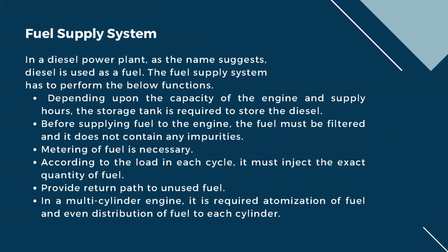The next one is, before supplying fuel to the engine, the fuel must be filtered so it does not contain any impurities. Next is metering of fuel is necessary. Next is, according to the load in each cycle, it must inject the exact quantity of fuel. Next is to provide a return path to unused fuel. And the last one is, in a multi-cylinder engine, it requires atomization of fuel and even distribution of fuel to each cylinder.